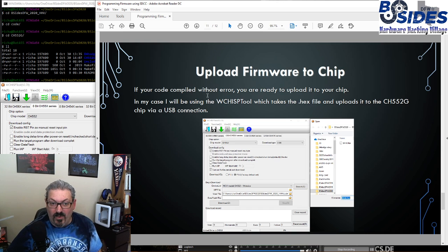And so to upload the firmware, we're going to open up the WCHISP tool or whatever other tool you're using. You're going to make sure that it recognizes your device, then load whatever file you want to put on there, and click, in this case they call it download. I call it upload because I'm taking it from my machine and uploading it to the chip, but that's a relative term, so some people call it downloading it to the chip. However you reference it, you're going to click the download button and it's going to push it to the chip, and then it'll let you know if there's any kind of errors.